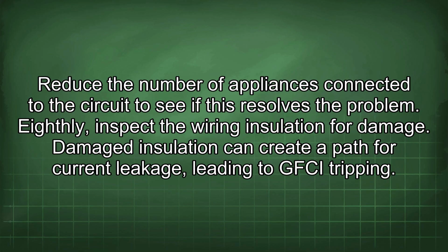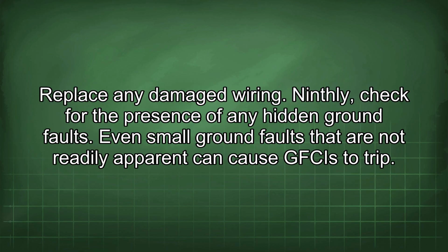Eighthly, inspect the wiring insulation for damage. Damaged insulation can create a path for current leakage, leading to GFCI tripping. Replace any damaged wiring.